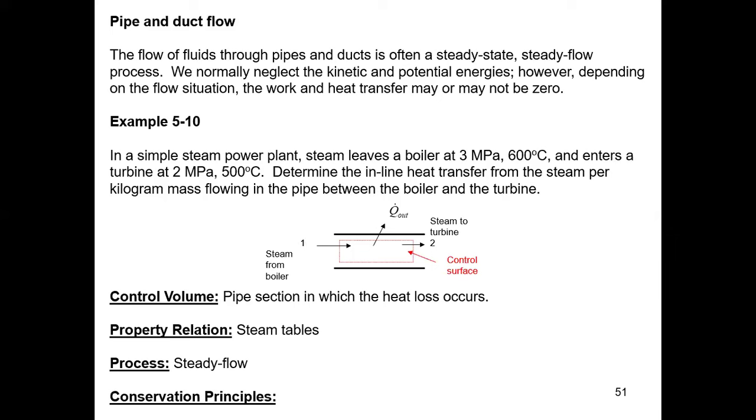Okay. Another problem: the flow of fluids through pipes and ducts is often a steady state, steady flow process. We normally neglect the kinetic and potential energy. However, in conservation of energy for the fluid, work and heat transfer may not be zero.